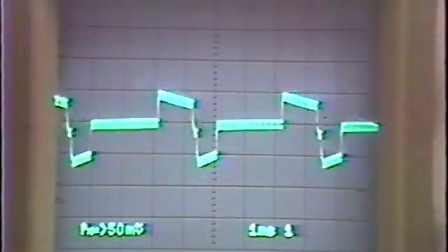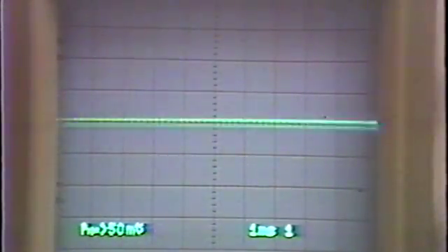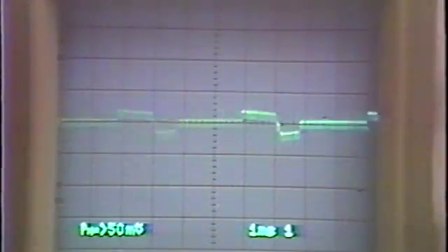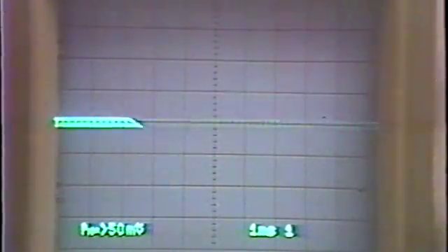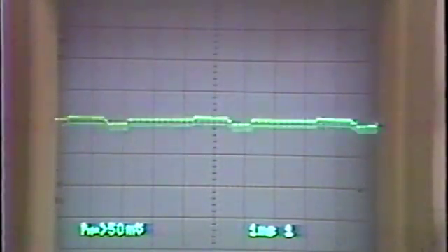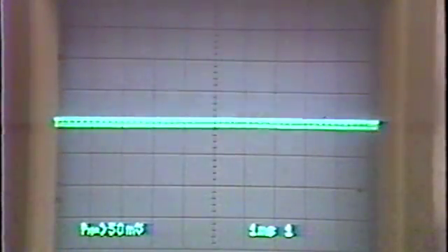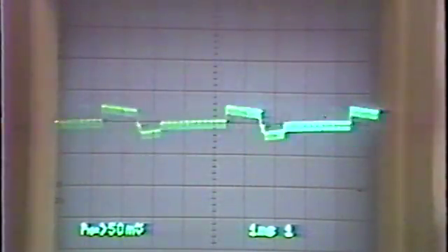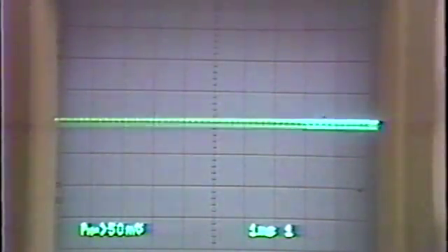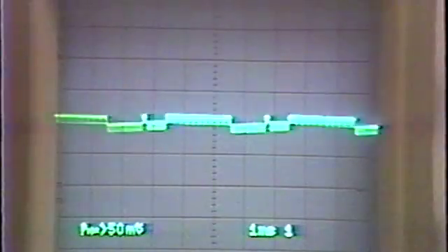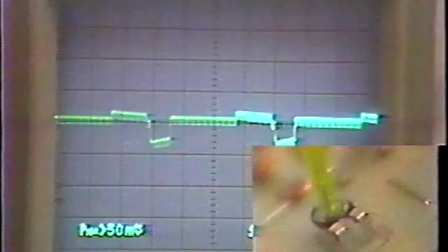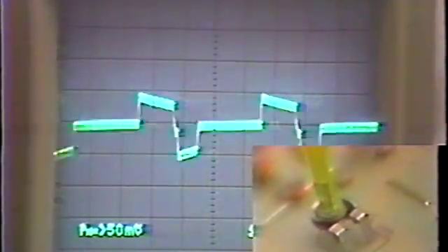When a key is pressed, the digital to analog converter output waveform appears at top and bottom, gradually becoming smaller and finally disappears. Adjust so that both disappear at the same time. Here the top waveform remains, indicating that the sound is prolonged more than necessary. The bottom waveform remains in this case. Adjust the variable resistor of the bit compensator so that both the top and bottom waveforms disappear at the same time.